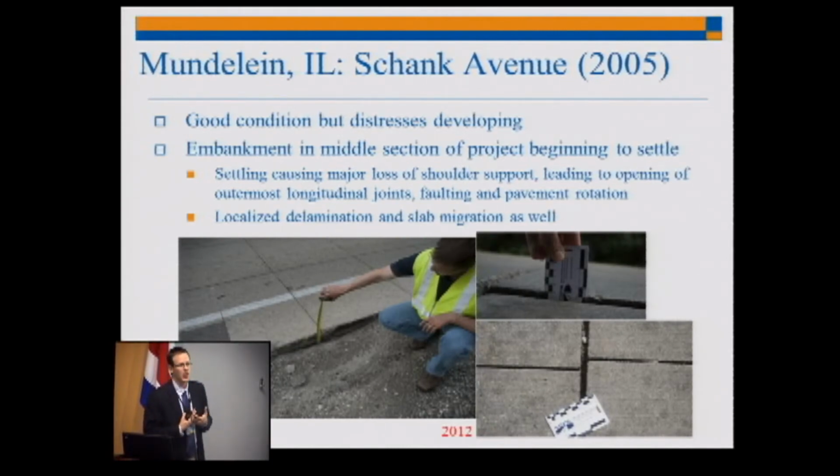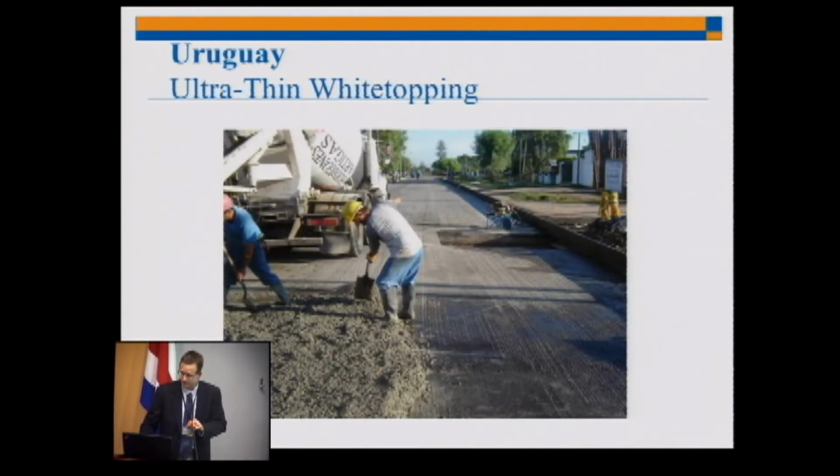So one of the things with concrete overlays, especially thin ones like this, is that the owner has to expect that after a certain number of years, you're going to see cracks. People generally think concrete shouldn't be cracking ever, or something's wrong. But with overlays, you're going to have some level of cracking because the designs are 15 to 20 years. So you're going to see cracks after 10 years for sure. The question is whether the cracks are going to deteriorate or not, and that's why we add the fibers also.